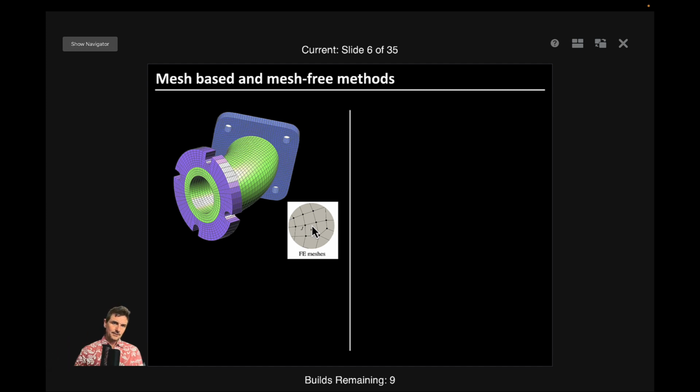Second role. So what is the second role of a mesh? Why do we need a mesh? Well, usually we use a mesh because we need integration points, like psi G here, right? So what are those things? There are points that you use to integrate the weak form, because you have a weak form. Contrary to what I just presented about point collocation, you have now a weak form, and the weak form needs to be integrated somewhere or other. And we use the Gauss points to do that.